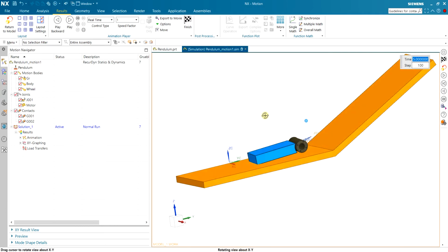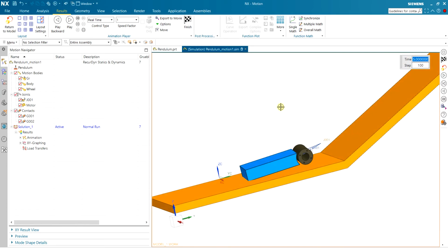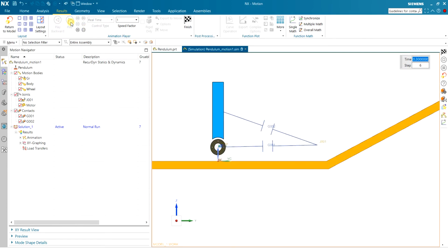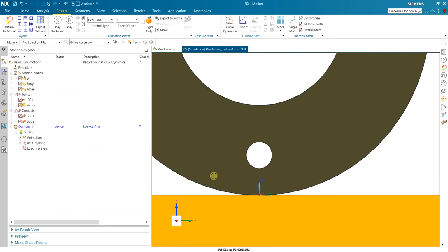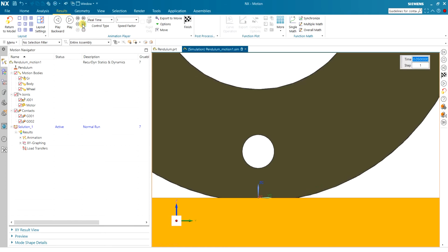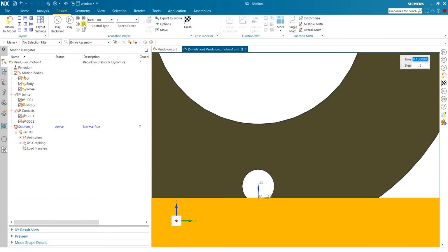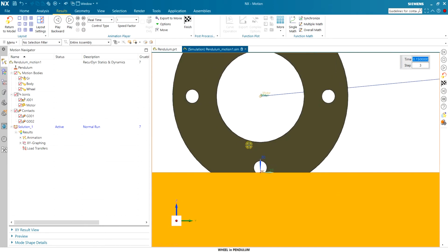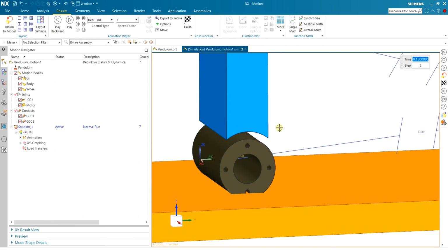The movement is somehow as expected, but it seems too bouncy. So to have a quick look, you can go closer, and if you look here, the problem seems to be with the initial penetration. It happens in the first, yeah, here. Here we have too much penetration. The contact calculation is a bit complicated. I have another lecture on this.